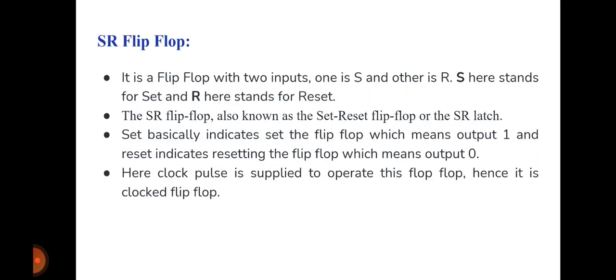SR flip-flop. What is an SR flip-flop? It is a flip-flop with two inputs. One is S and the other is R. S here stands for set and R stands for reset. So SR flip-flop is abbreviated as set and reset flip-flop.